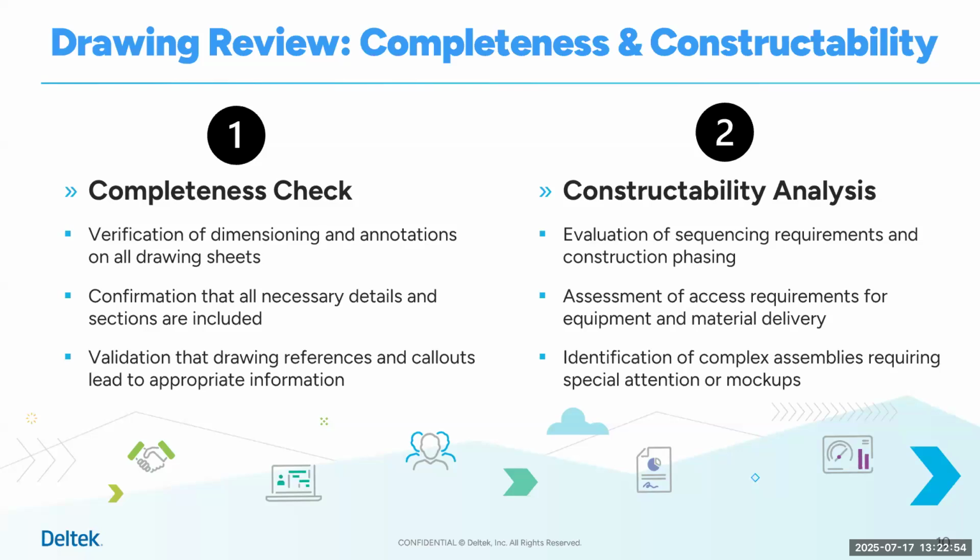Also, with the constructability reviews or other reviews, it may involve some cross-checking for discrepancies across the disciplines. The things that are shown on the architectural drawings, are they coordinated with the structural drawings and the MEP drawings, being mechanical, electrical, plumbing, and any specialty systems that may be involved?